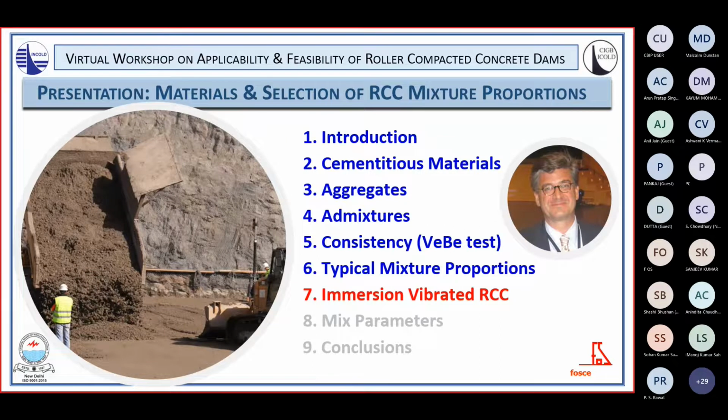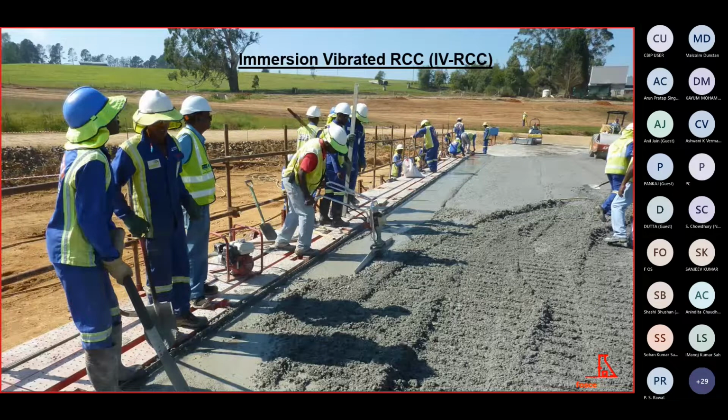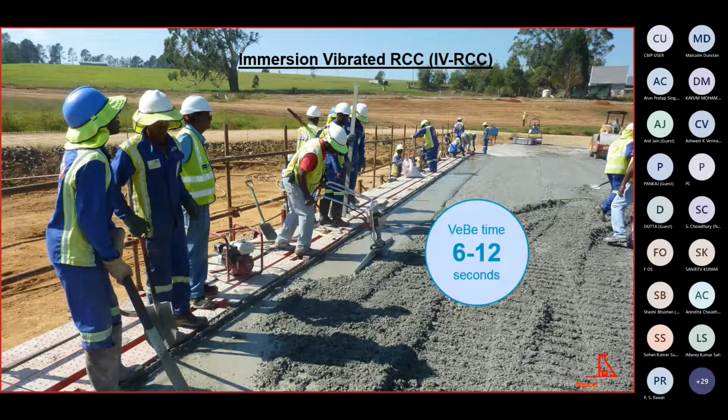Let's take now some time to introduce IV-RCC, immersion vibrated RCC. This picture was taken during construction of the full-scale trial leading to the construction of Spring Grove Dam in South Africa, completed in 2012. A very workable mix was designed with a VB time between 6 and 12 seconds. The mix has a total content of cementitious materials of 160 kg per cubic meter, of which only 50 kg per cubic meter is cement, and the remaining 110 counts for a locally available fly ash.